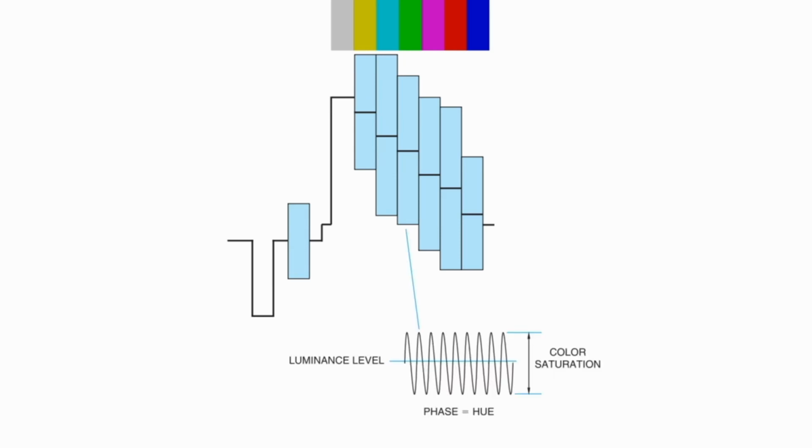But first, no, we're not experiencing technical difficulties. It turns out if you can understand this test pattern, it helps you understand video on the Apple II. The waveform for one line of these color bars looks like this. If you looked closely at the blue regions, you see they were high-frequency sine waves, around 3.6 megahertz. So the first clue is that white is a flat line, and solid colors are rapidly oscillating signals.